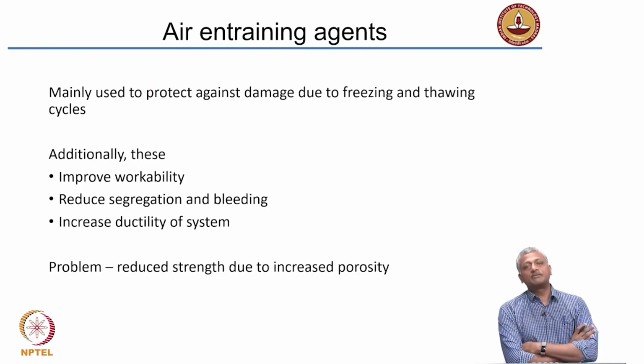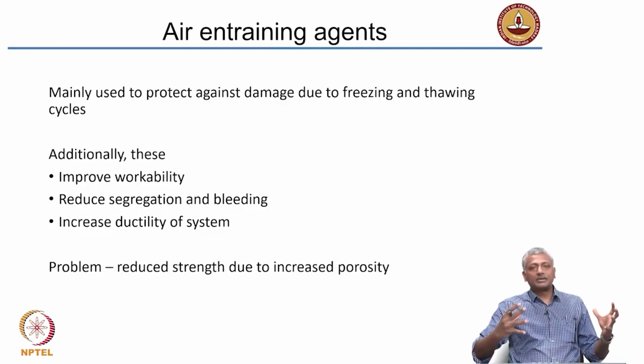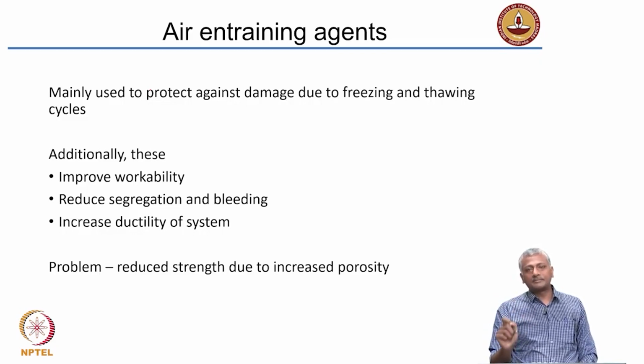You have an anomalous behavior with water. When you freeze it, it expands. And this expansion leads to stresses in the concrete causing cracking. So, in such cases, what we do is we put very small air bubbles in the concrete. Air entraining agents create small air bubbles in the concrete that provide a space for the water to convert to ice and expand. So, that reduces the stress in the concrete and reduces the cracking.